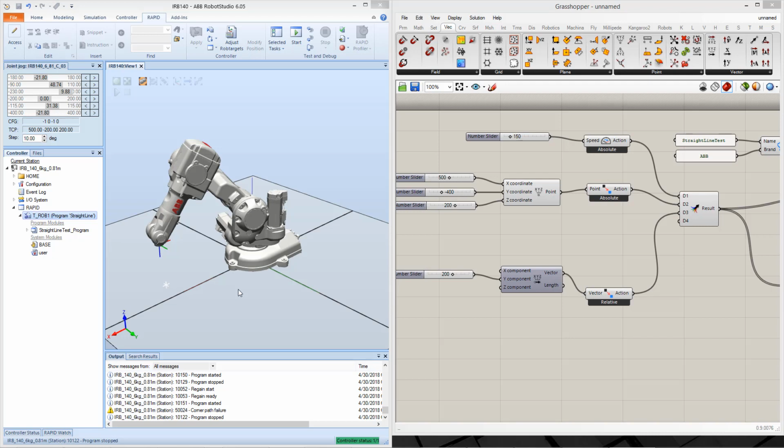So, for example, we may want the movement of getting close to the paper, to the first point, to be very fast, but then we may want the movement of drawing the line to be much slower than the approach velocity. And also, it's good practice, once you have finished executing your program, to move the robot back to a home position, to a relaxed position. So that's kind of what we're going to do right now.